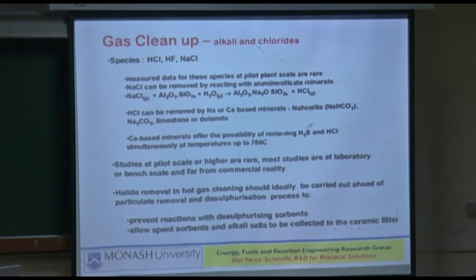Most studies are at laboratory or bench scale and far from commercial reality. I think if what you're going to have is a large bench scale, that's good. Halide removal in hot gas cleaning should ideally be carried out ahead of particulate removal and desulfurization process. Why? To prevent reactions with the desulfurizing solvents and allow spent solvents and alkali salts to be collected in the ceramic filter. So that's common sense.